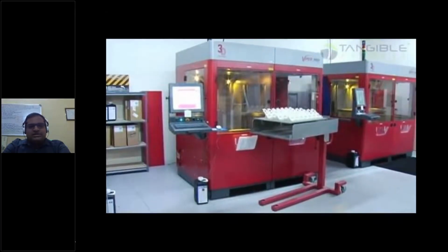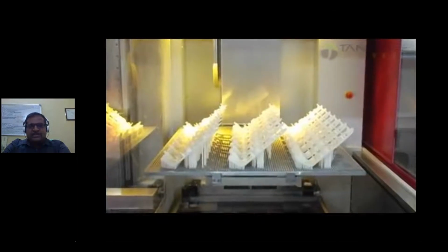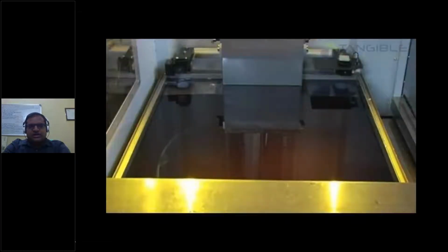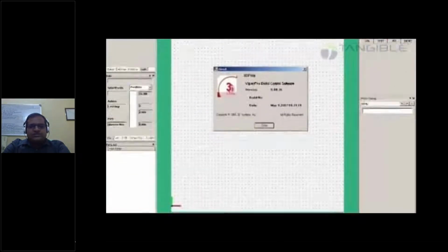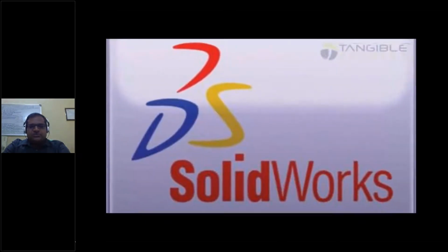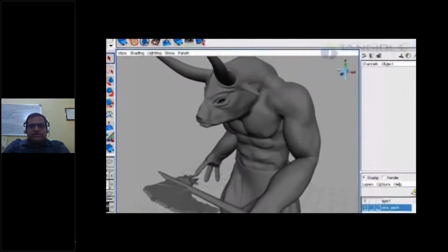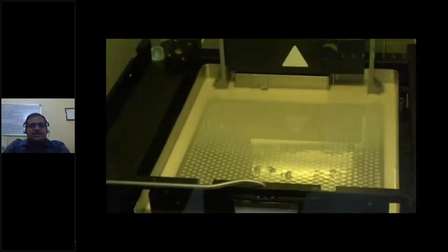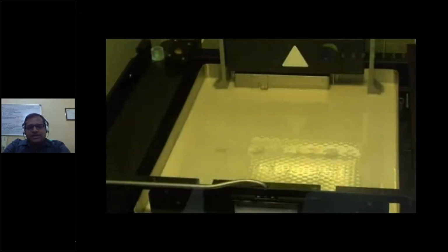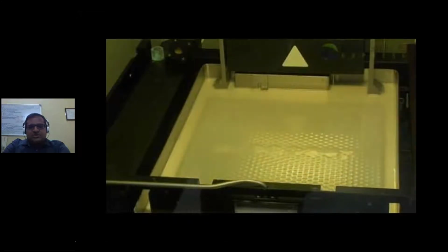As I already mentioned, the raw material is in liquid form, and you use a laser to cure as per the design or as per the slice data. So what we have to do is first start with solid modeling software to make the CAD model, or even video gaming data or whatnot. It may be medical data or it may be scan data, but you send that, and then based on that cross section, now you can see.